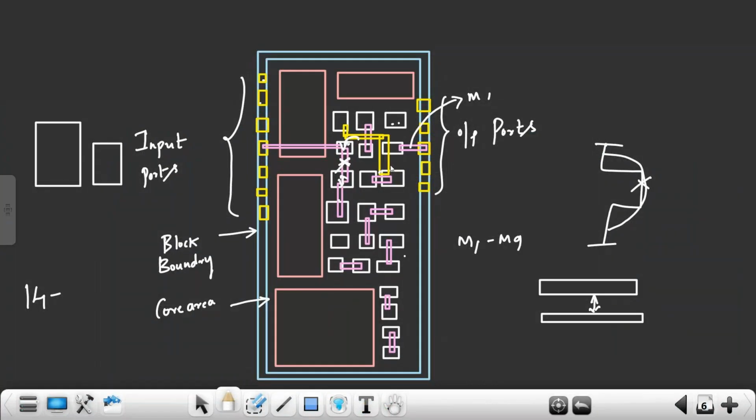I have to check whether 14 nm is going to support the cells which are running with 1 gigahertz. Means cell should operate very fast. If the cell should operate very fast means cell should take more VDD. What is the VDD limit for the technology? We should check that. So that is all constraint dependent.